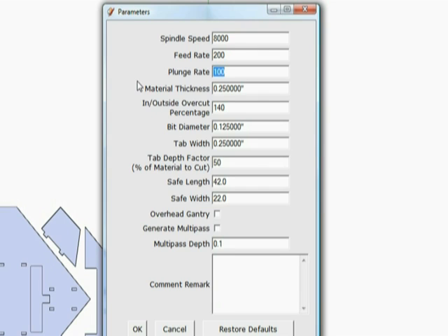And I won't give you too much on CNC theory other than the fact that you need to understand your machine's capabilities. Your machine, if you're using an original flat printer, what some of us have called an MK1, well, most of those machines are not capable of 200 inches per minute. And at any rate, you'd want to set up the rate at what you know your machine can do. In this case, again, I'm setting up 200.